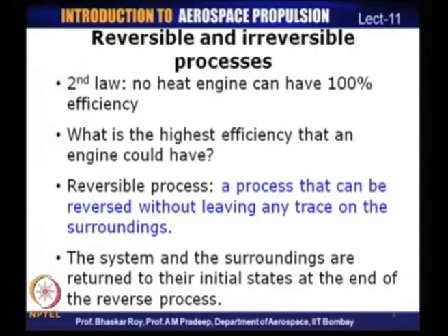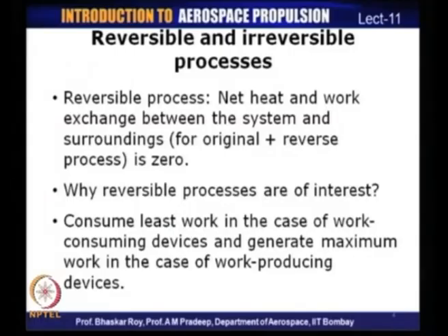So, to define the highest efficiency associated with any cyclic device or heat engine, we will need to define basically reversible processes. In a reversible process, the net work and heat exchange between the system and the surroundings, which includes both the original and the reverse process, will be 0. And so, in a reversible process, since the net heat and work exchange between system and surroundings are 0, you might wonder then what is it that makes reversible processes of interest?